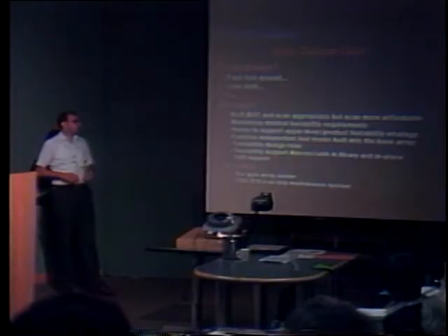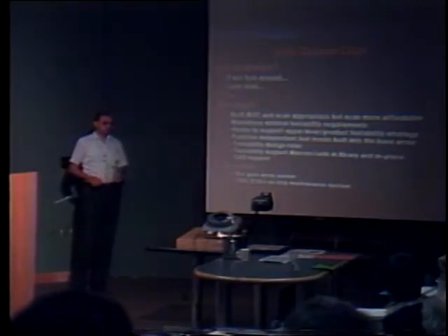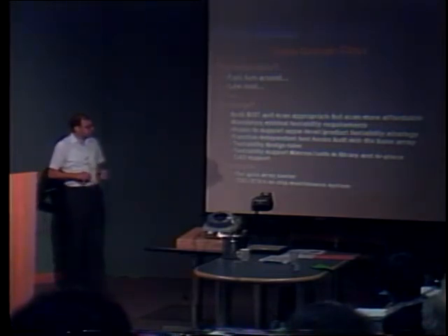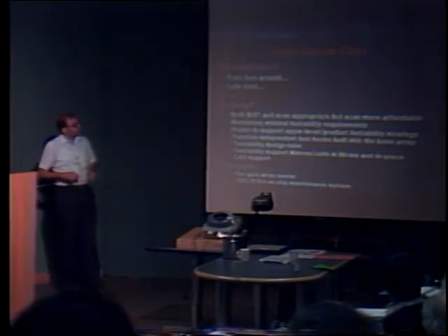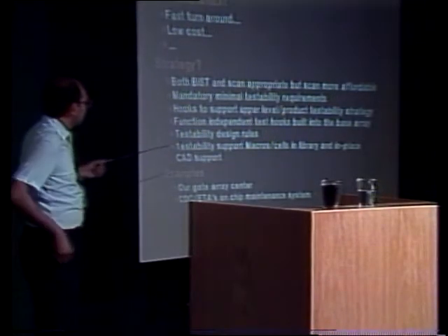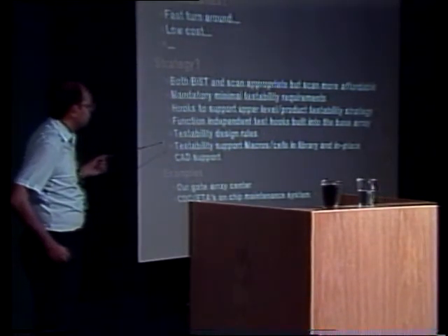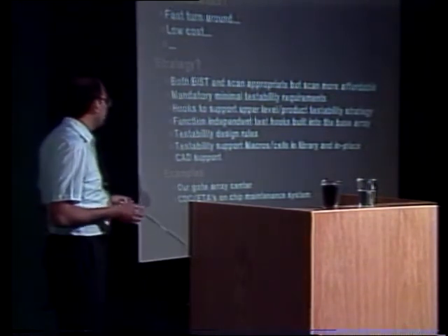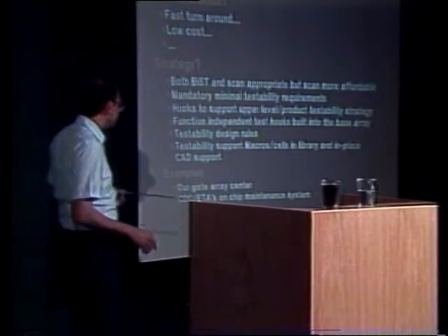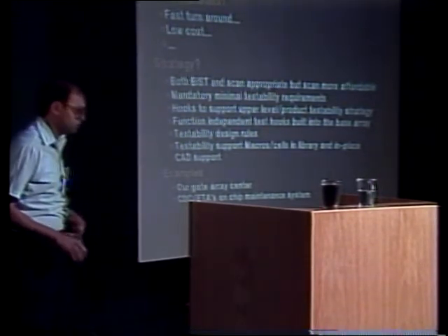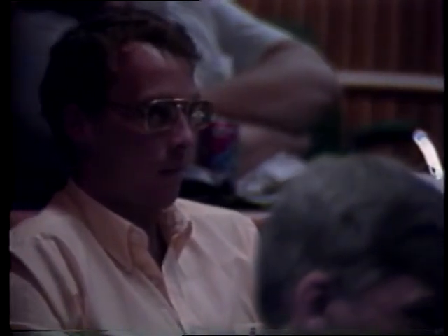We do have some of this in DEC, and you will see some of it tomorrow during the CAD session. Now, again, implementing testability on the semi-custom chips, we can think about function-independent test hooks, which may be built on the base array. One such example is CDC and National's on-chip maintenance system.